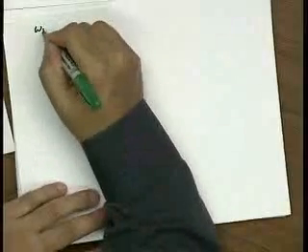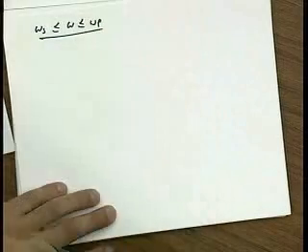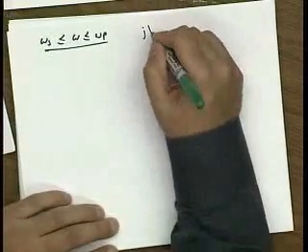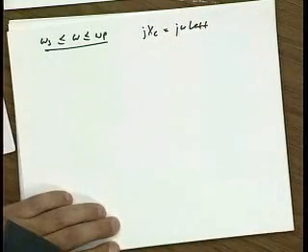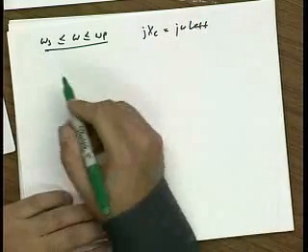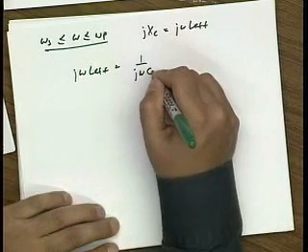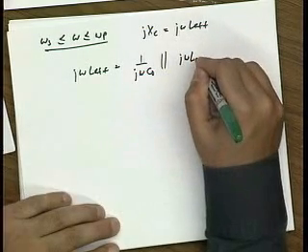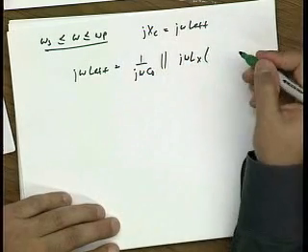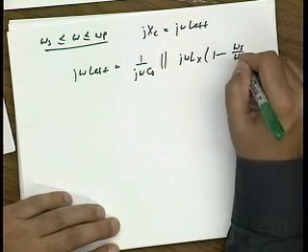Crystal clear. All right. So how about in this frequency range that we so care about? Well, in this frequency range, clearly it's an inductor. And the effective value of inductance, we calculate it in the same way. We have an external physical capacitor in parallel with a series circuit, series resonant circuit. So now I factor out j omega Lx to keep this term positive.